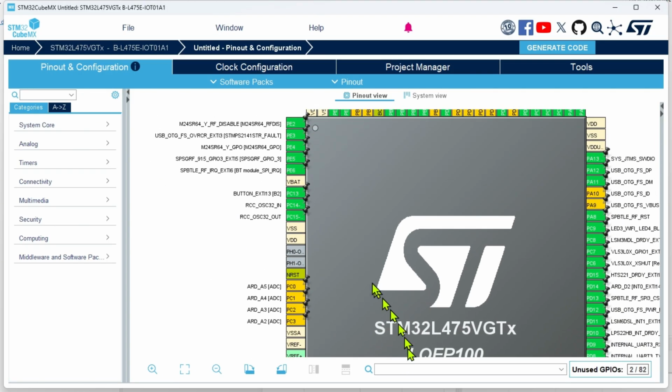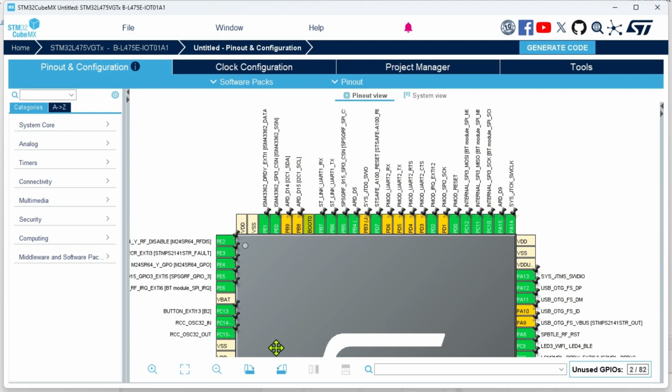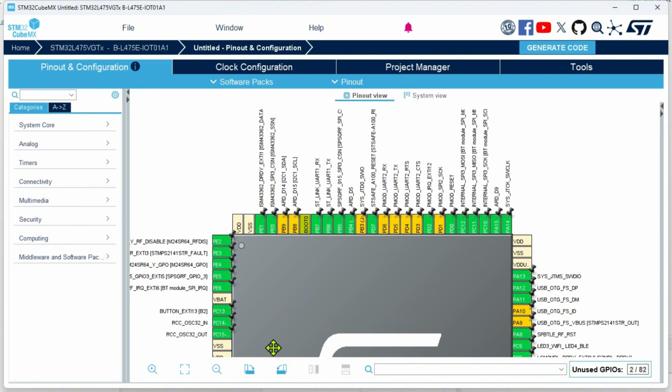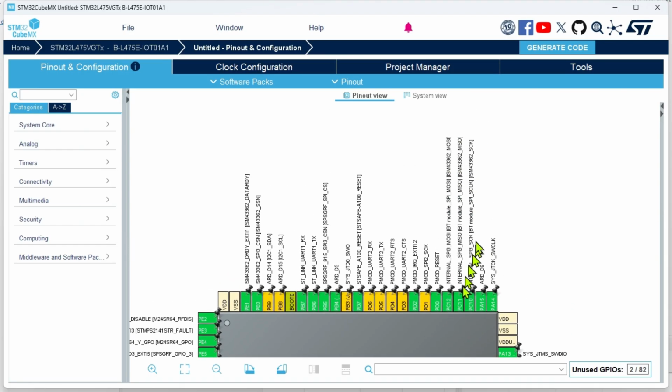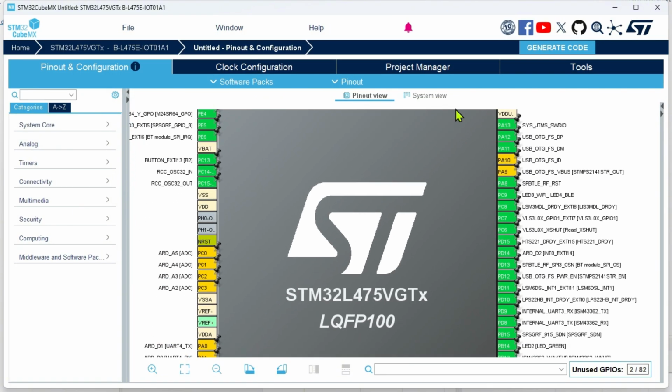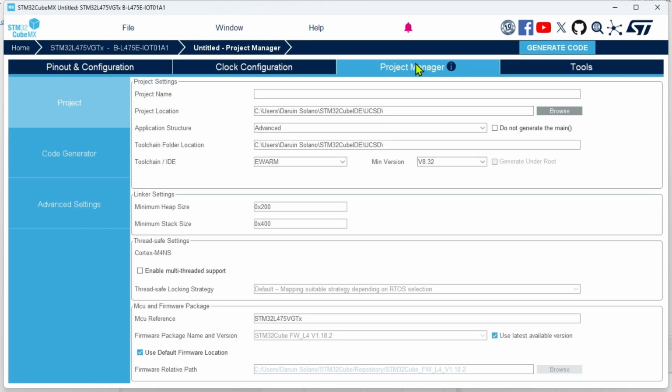As it is pin 1, we're gonna be activating the EXTI1 interrupt in the chip. Also, the SPI3 is the communication module that we're going to be using from our silicon. Okay, so SPI3 needs to be activated in the same way. Also, SPI3 interrupt needs to be activated. But first things first. So let's select first the type of project we're going to be using.